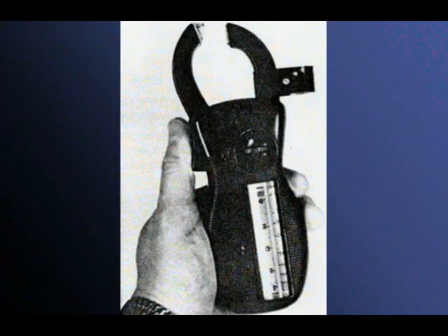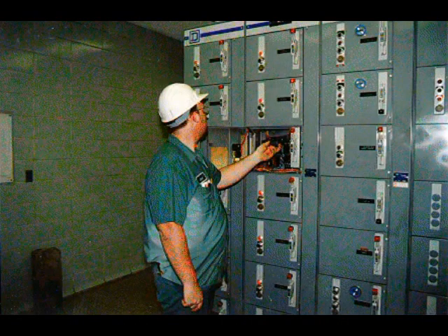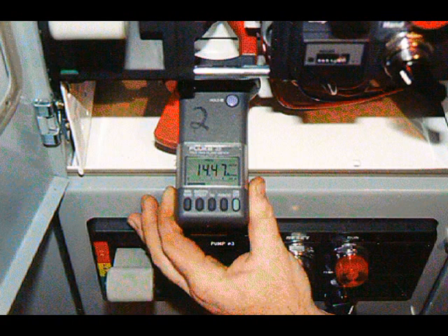Ammeter readings are another main source of information about pump motors. Ammeter readings should be monitored and recorded regularly. Some motors do not have ammeters. In these cases, an electrician should regularly check the current drawn by each of the motors and record that information. If a motor starts drawing more electrical current than normal, problems can be anticipated.